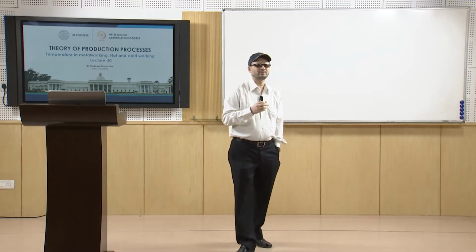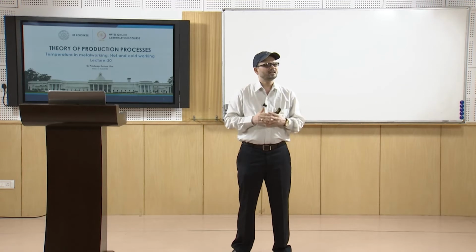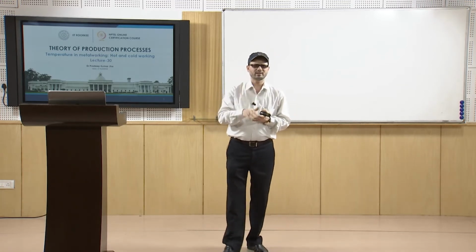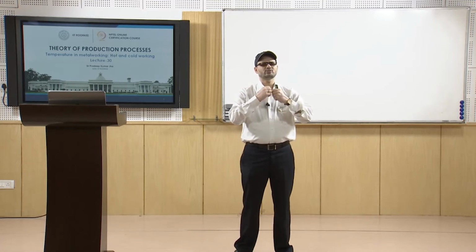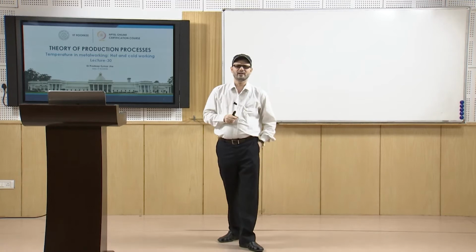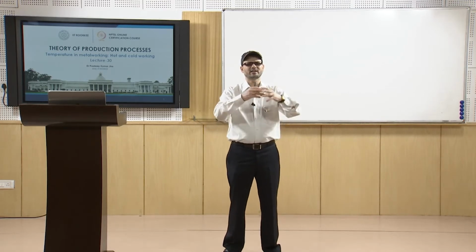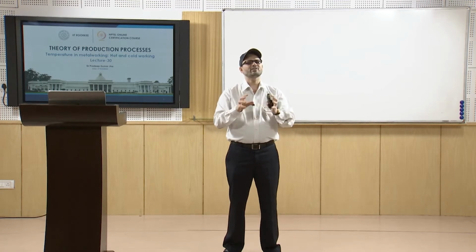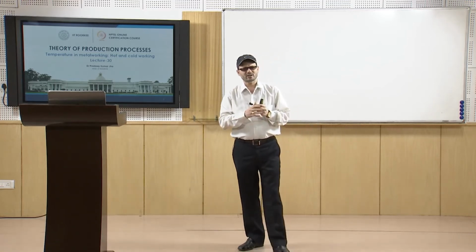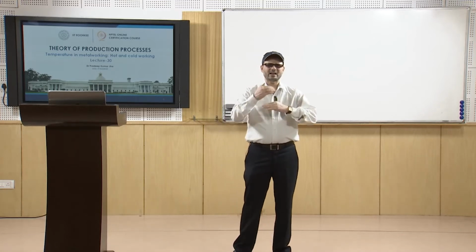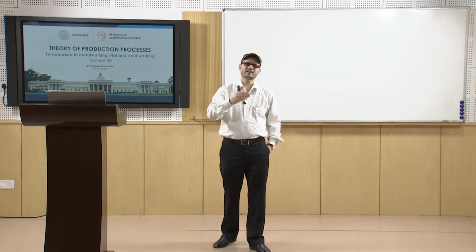In the case of cold working, recovery does not take place. The grain which is strained is deformed and the strain energy is stored, so a lot of energy goes into the material, and that strain field is not relieved. That is why, when we do cold working of the material, the grains are quite elongated and distorted. Strain hardening takes place, and because of this strain hardening the strength is increased.